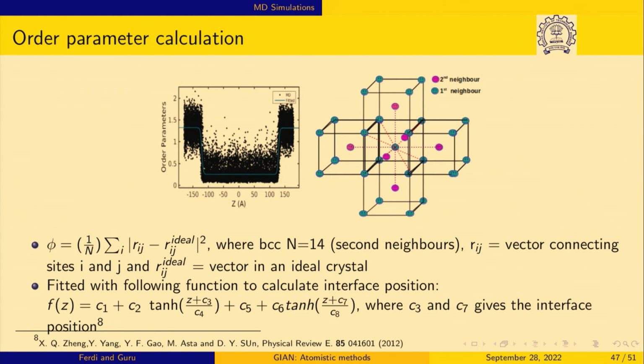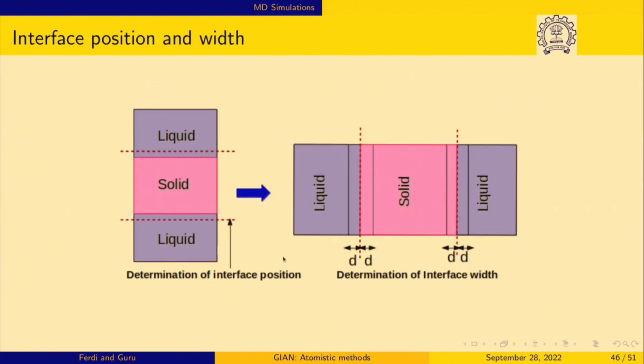Just to make sure that we do not have too much error, we take a region, that is what is shown in this. So, we take a small d about the interface, where I make sure that I enter well into the bulk on both sides, that is all I make sure, and that we found is about 20 angstroms. And given that iron lattice parameter is about 2.5, 2.3. So, this is about 5-6 unit cell distance on either side you have to go to make sure that you are well within the bulk region. If you assure that, then your calculation will give consistent interfacial properties, that is there from the formulation.